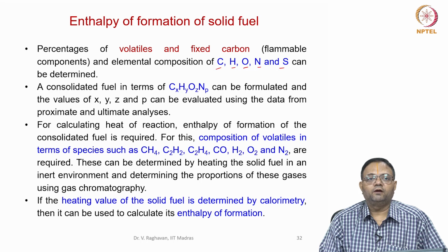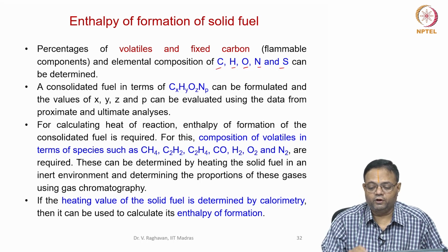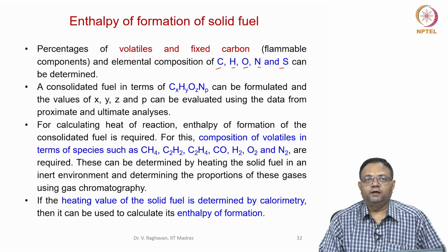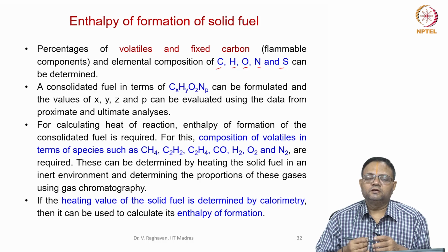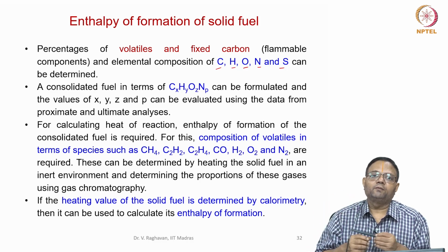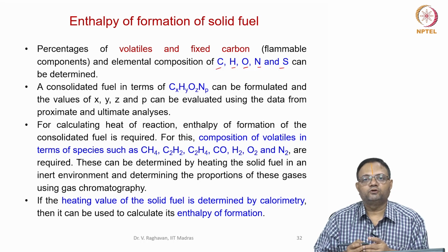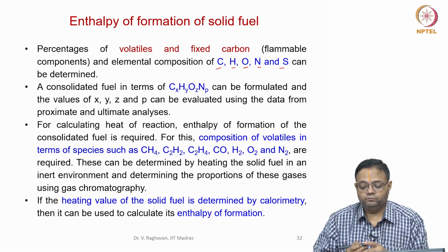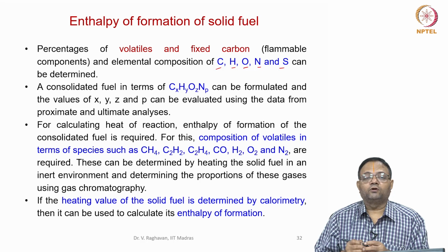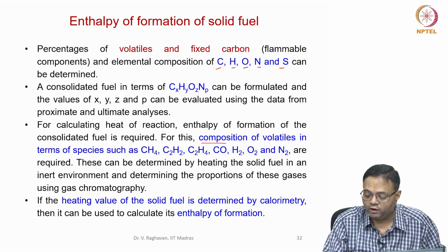For calculating the heat of reaction, you need the enthalpy of formation of this fuel. For the multi-component mixture constituted by LPG, since the individual components' enthalpy of formation was known to us, we calculated the enthalpy of formation of LPG by using a mixing rule, sigma Xi HFi. But in order to calculate the enthalpy of formation of volatiles, I need the composition of volatiles.